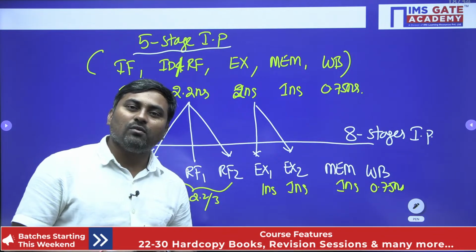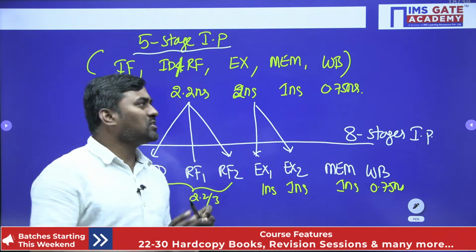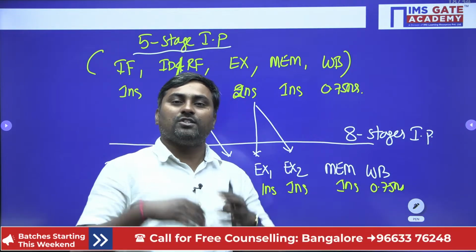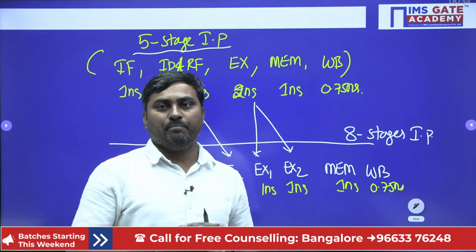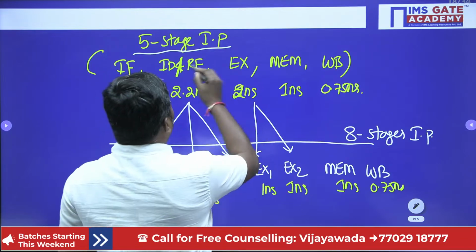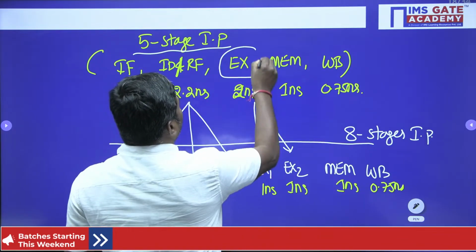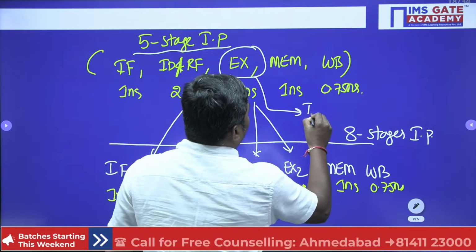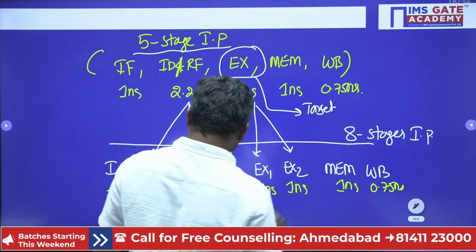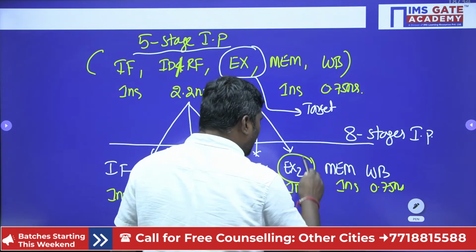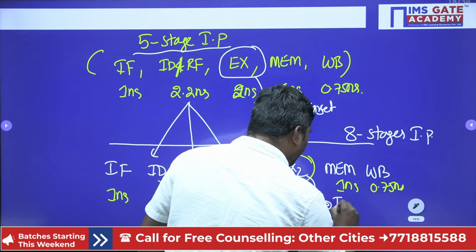What are they asking? They are running some instructions in the two pipelines, and in these instructions, 20% are branch instructions. Now the branch delay needs to be computed. One piece of information you have to understand: in this case, the branch instructions are evaluated by which stage? The execution stage here, which produces a target address. In the new design, who is going to generate the target address? The execution stage is going to generate the target address.